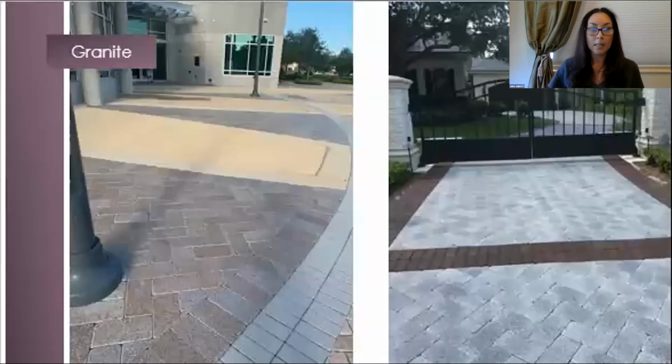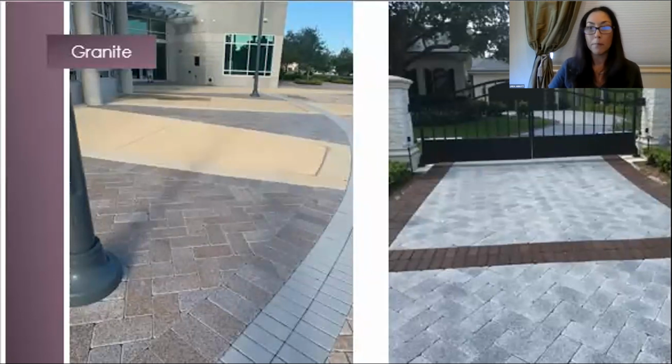Granite can be a fabulous natural stone option for driveways and commercial high-traffic areas. You'll never hear me suggest this volcanic natural stone option for pool decks though, because you will not enjoy walking around barefoot on hot sunny days. The beauty of travertine, marble, coral stone, and limestone are perfect for pool deck materials to enjoy barefoot by the pool.